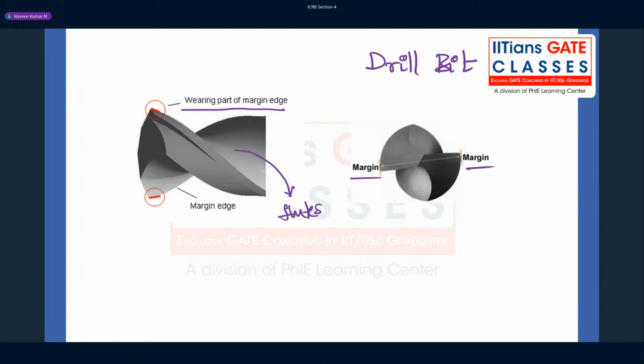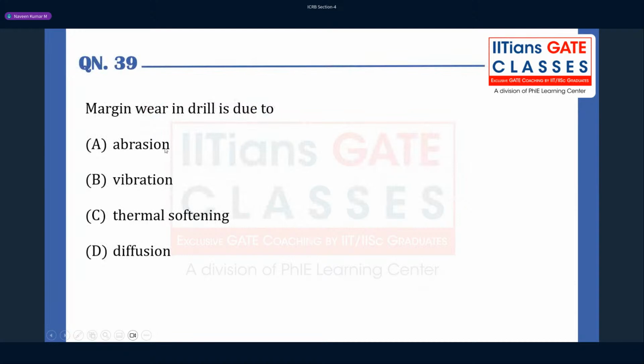Why are these flutes provided? These flutes are provided to help the chips come out. Otherwise, where will the chips go? Right? That's the thing. So it's not due to vibration.